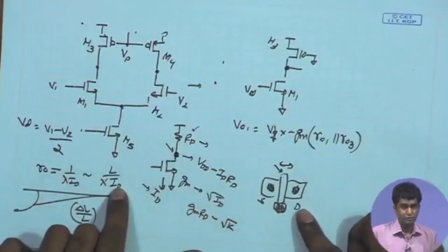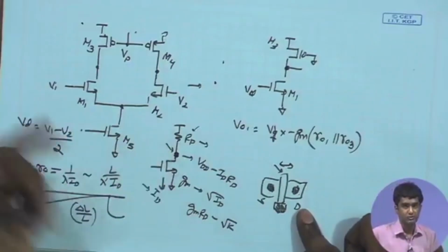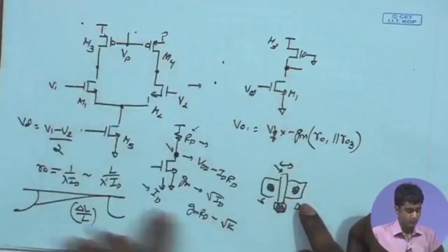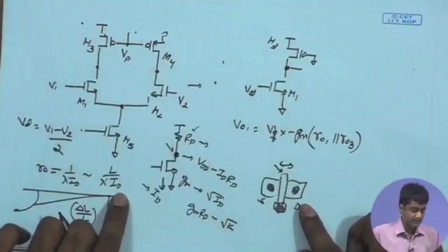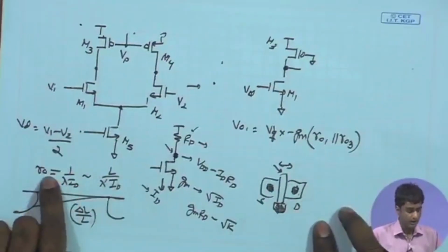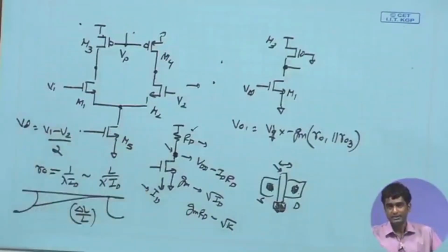And the other strong option that I have for increasing the gain is the ID. I can lower the bias current in the circuit to achieve larger gain. So there I can use active load, I can employ smaller and smaller bias current and longer channel lengths to have a large RO and at the same time get large gain without sacrificing the area significantly.